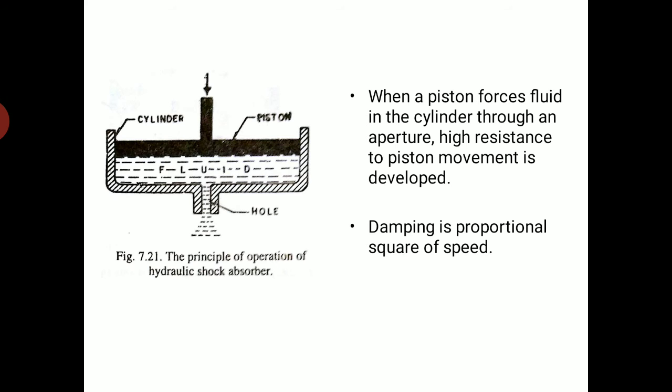Such a spring action on the car would produce a very bumpy and uncomfortable ride. It would also be dangerous because the bouncing wheel would make the car impossible to control. This would be especially dangerous on a curve. Therefore, a device is needed to control the oscillating action of the spring. This device is known as a shock absorber. There are many types of shock absorber available, such as vane type, opposed piston, and telescopic. The telescopic shock absorber is most commonly used, so let us discuss exactly what this telescopic shock absorber is.